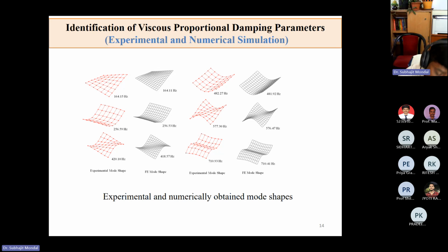now what is going to happen? If you go for viscoelastic damping, you will observe that our solution comes as a complex term. In that case, E is equal to E real plus E imaginary. If you have an E which is a complex term, then as engineers we will find it very difficult to model. So for the same reason, many people try to model it as viscous damping, and it has been observed that viscous damping also shows good results in the dynamic analysis of a composite.